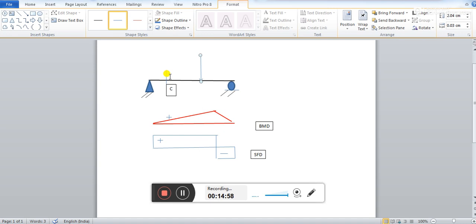And if we want to find out deflection, bending moment, shear force, reactions at a particular point in a structure or structural element because of the moving load or rolling load over the structure, then the concept through which we should be able to get it directly is actually called influence line.